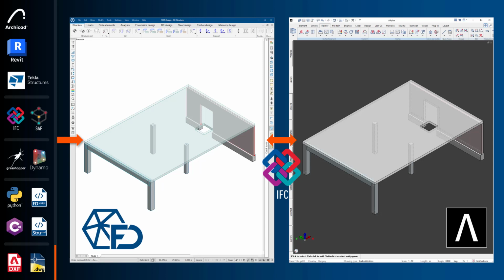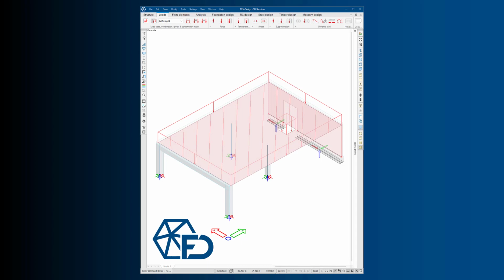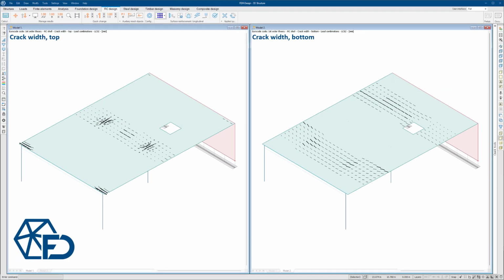In this example, the initial model was converted quickly from a concrete formwork model, created and exported with Allplan. We can then build the final analytical model by setting the final position of the objects, like eccentricities, the concrete materials with physical properties, like time-dependent parameters, and by adding the supports, the connections, the loads, and the load combinations. FEMDesign enables us to design and check concrete objects by modeling and considering their realistic behavior, like cracking, shrinkage, creep, elasticity, post-tensioning, and fire resistance.